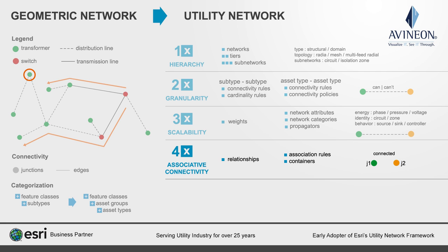Are you ready for the last in our list? With utility network, junctions can have in and out terminals. It is a smart way to represent incoming and outgoing ports on equipment without actually drawing ports as graphical features on the map. Terminals are the implementation of network graphs and logical connectivity gateways. This makes it possible to emulate multidirectional flows at a junction by simply placing equipment as a point in the map and specifying the terminal configuration. This compelling feature does not exist in geometric networks and is an important capability to many utility end users.